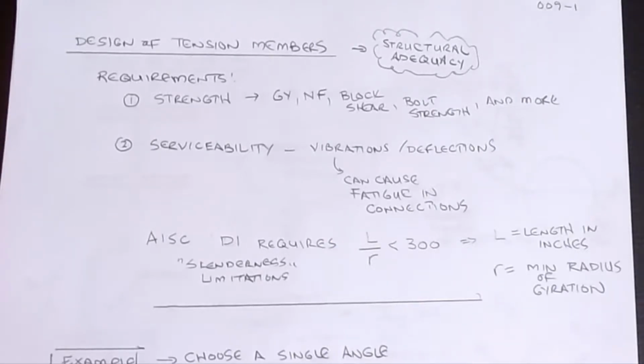But there's a second one in there that is not strength related, and that is what is known as serviceability. Serviceability affects things like deflections or vibrations or usability of a structure. Things that are a little bit harder to quantify but do have an impact on how a structure is used or its perception of quality.